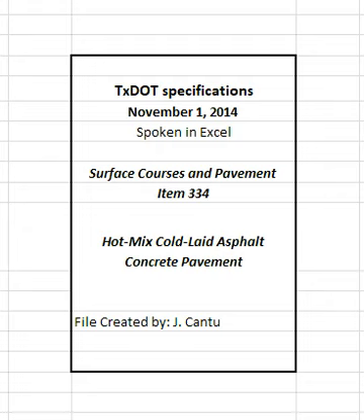Ensure that the mixture leaves the plant in a workable condition. Provide materials that remain workable in a stockpile for at least 6 months. Submit a new mixture design at any time during the project. The engineer must approve all mixture designs before the contractor can begin production. 4.1.2 Job Mix Formula Approval.